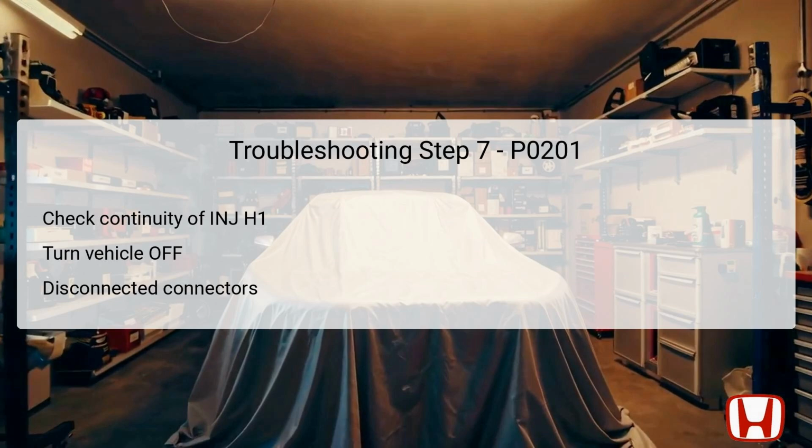A yes response indicates that a short condition is present and requires immediate repair. However, a no finding means that the INJH1 wire may be functioning as intended, which could lead you to move to step 8 for further continuity checks.